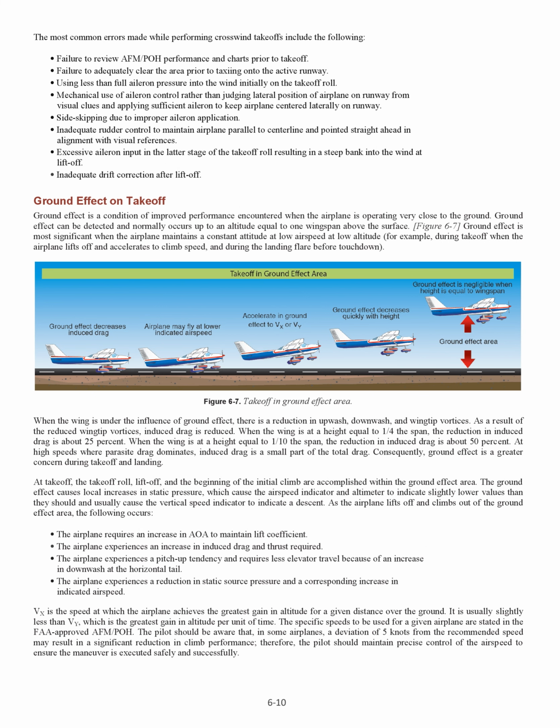Side skipping due to improper aileron application. Inadequate rudder control to maintain airplane parallel to centerline and pointed straight ahead in alignment with visual references. Excessive aileron input in the latter stage of the takeoff roll resulting in a steep bank into the wind at liftoff. Inadequate drift correction after liftoff.